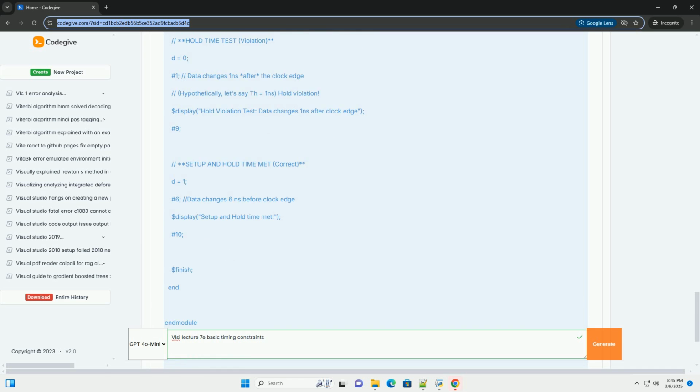Explanation of the test bench. 1. Clock generation: always #5 CLK = ~CLK creates a clock signal with a period of 10 ns, a frequency of 100 MHz. 2. Initialization: RST_n is initially set to 0, active low reset, to reset the flip-flop. After 10 ns, it's released, RST_n = 1.